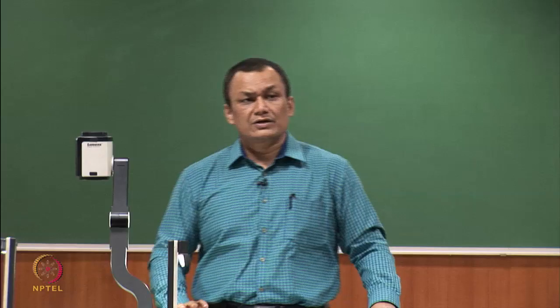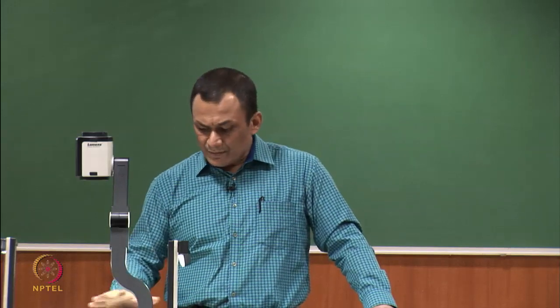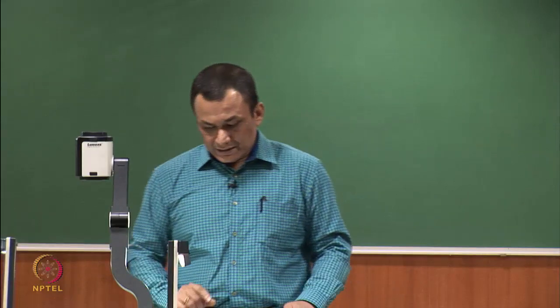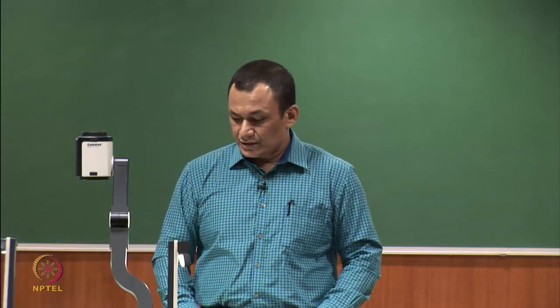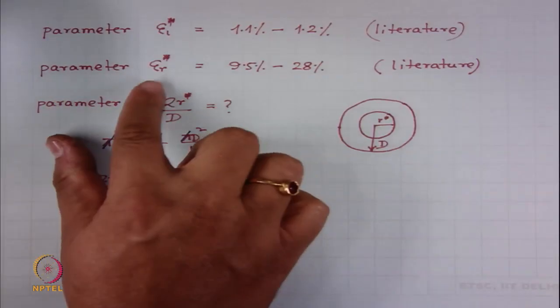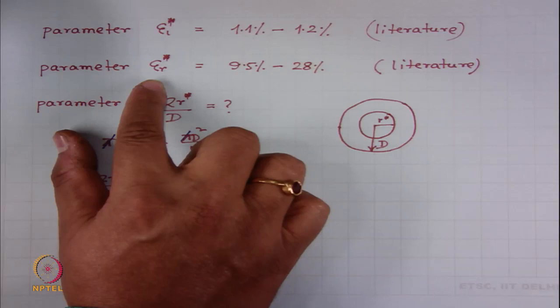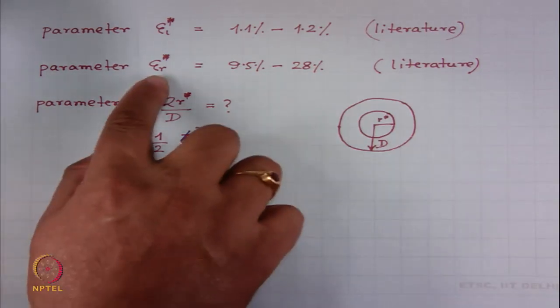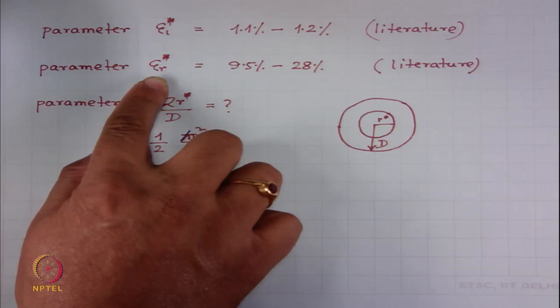For ring yarn, rotor yarn, air jet yarn, friction yarn, probably this value might be different. So, this was the discussion with 3 parameters. These parameters remain constant. This parameter, however, is a function of number of cycles of washing and drying. At the beginning this value will be less, as you go on washing and drying this value will increase, probably after certain number of washing and drying this value will not practically change.